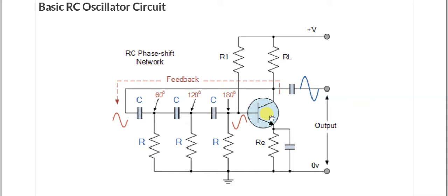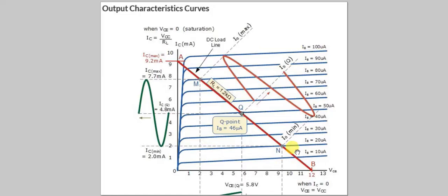We have discussed that quite at large during the amplification. So let me demonstrate: this is a typical load line of the common emitter amplifier circuit. This is VCC and this is IC. This is VCEQ. This is the Q point. Q point means quiet point or quiescent point, and this is ICQ. This is supposed to be the Q point where the transistor is biased and supposed to be staying at the middle. This is a class A amplifier. You can see it is in the middle of the load line. So this is the DC load line.